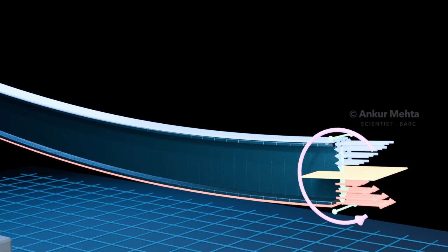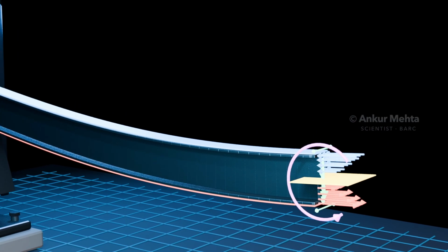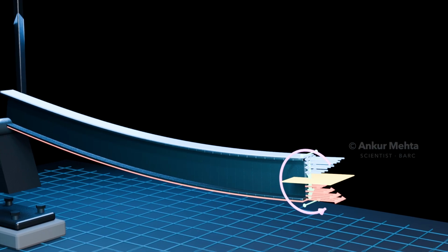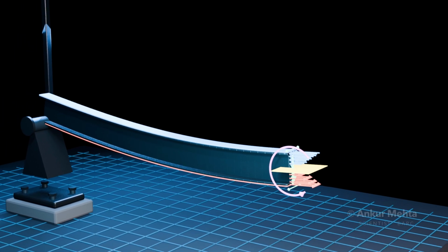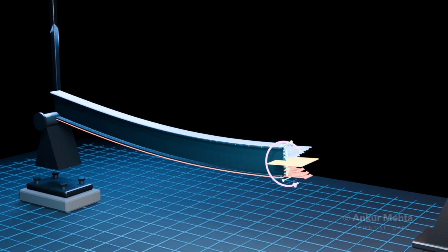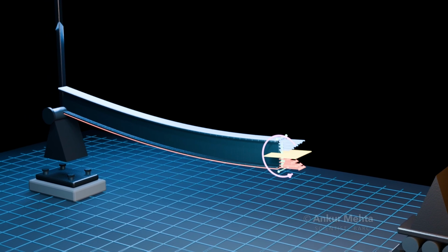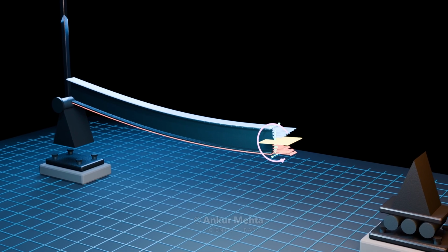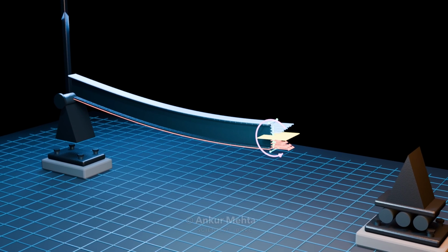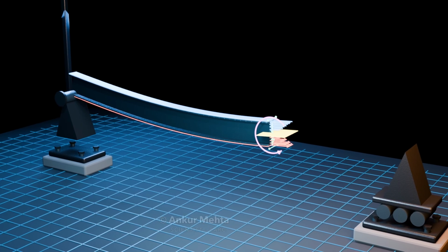The final view combines the complete response: applied load, support reactions, deflection, shear, bending moment, and cross-sectional stress. In design, these results are checked against strength, serviceability, shear capacity, lateral stability, local buckling, connection forces, and code requirements. Every arrow represents part of one continuous load path.